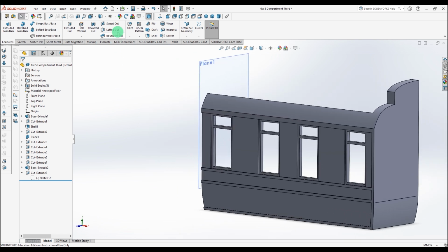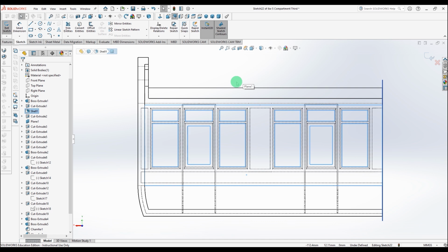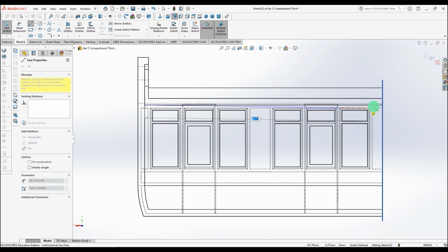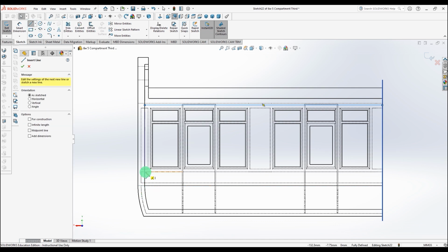Now we need to put some doors on here. Apologies, I've lost another piece of the footage, the bit where I actually show doing the doors, but the door windows are done exactly the same as the other windows, and the cutouts around the doors, the reveal, were done by simply drawing various rectangles and extruding them in.